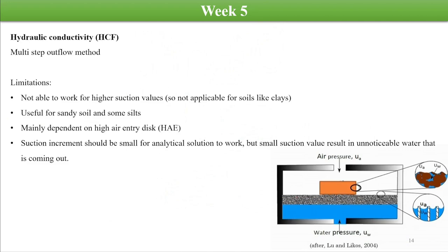Okay, but it has some limitations, in that we cannot work at higher suction values in this experiment. Okay, so it may not be applicable for clays. It is useful for sandy soils and some silts, mainly dependent on how much water can permeate, or how the high air entry disk is there.